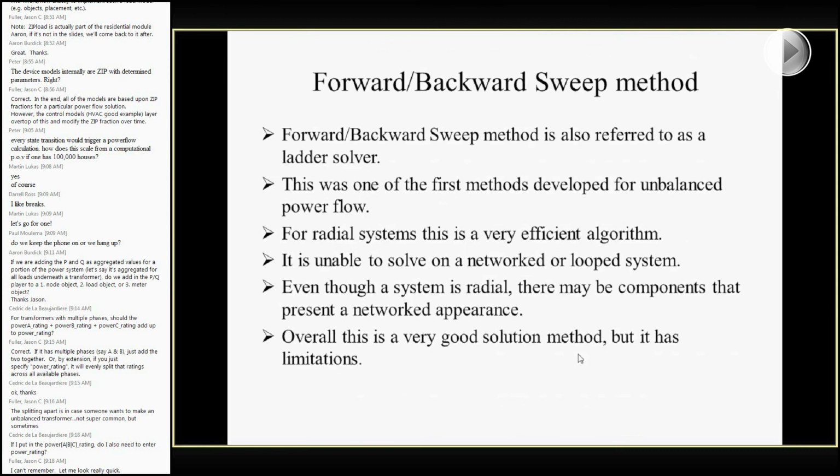So the forward-back sweep method, just to get into a little more detail, is also referred to as the ladder solver. You're basically working your way up and down the tree of the distribution feeder and either calculating the current injections or solving for the voltage at each step, depending on whether you're on the forward or the backward, or I guess the up or down ladder. This is one of the first methods developed for unbalanced power flow.